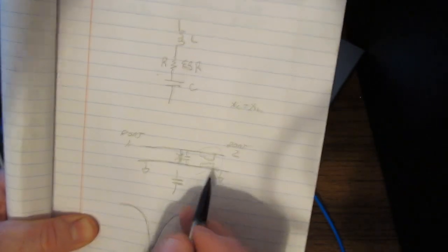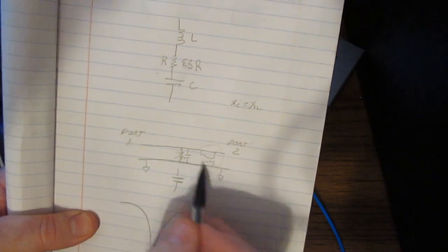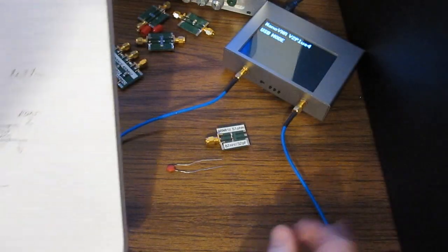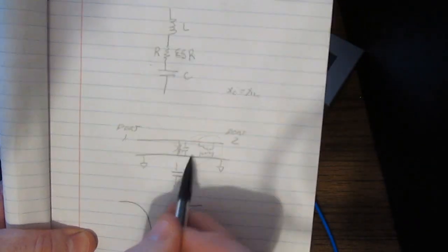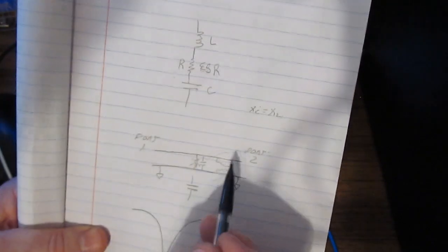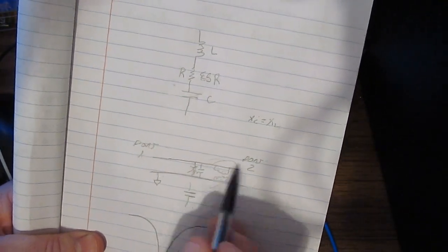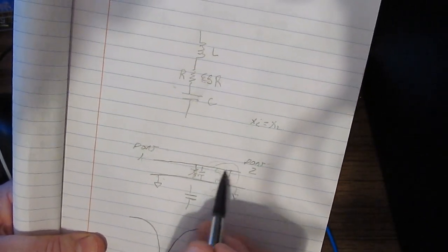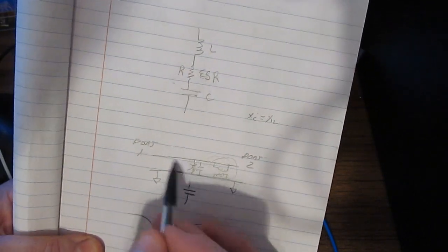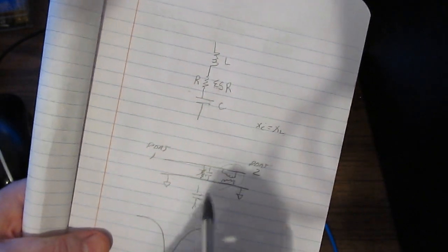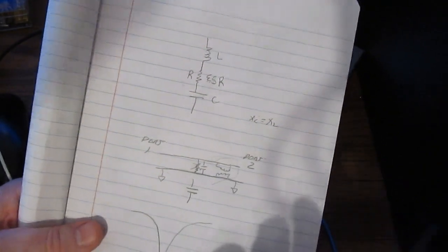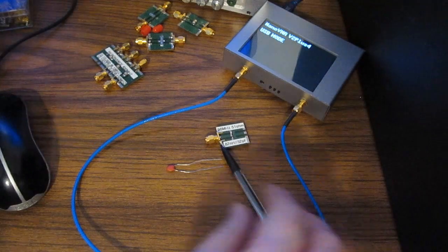And the whole idea of this is to make this braid lossy. Now again, we're working at frequencies where the cable itself is going to become quite lossy, so this isn't really going to pose a problem for this demonstration, so we don't have a need to really load this thing up. The other problem with making this measurement is, of course, there's quite a bit of port mismatch here. What you may find that you need to do to improve the return loss is add an attenuator to this side. You may actually have to do it to both sides to get a decent measurement. Again, it's going to depend on the range of the parts that you're trying to look at. You just have to experiment with it.